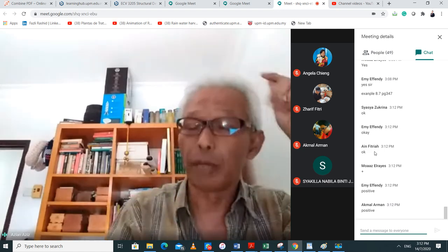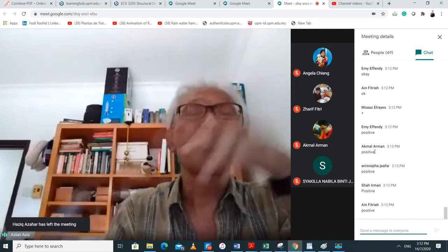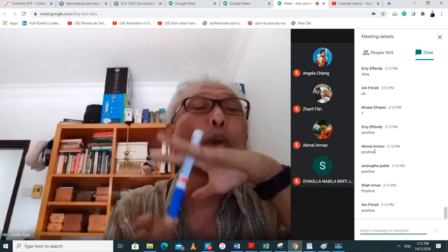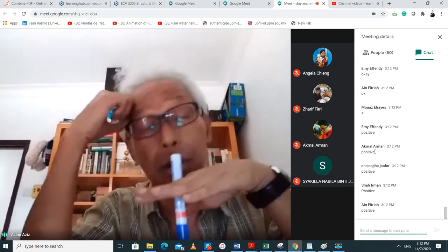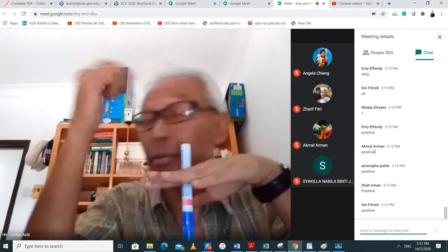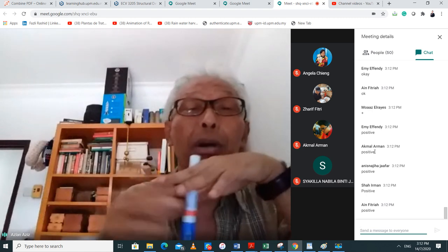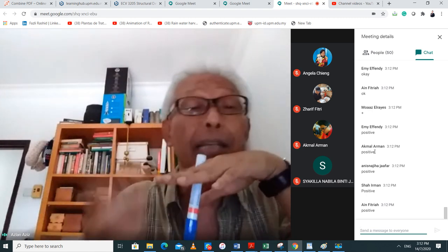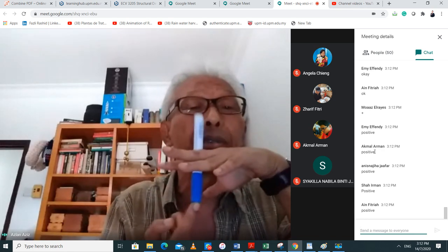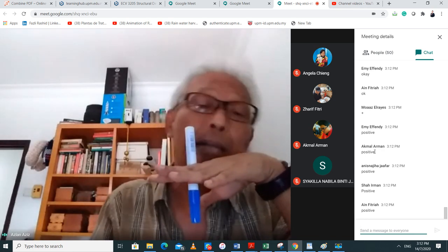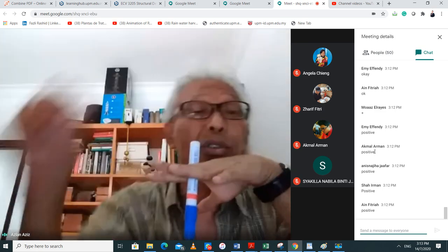Good for you, Muaz. So, positive direction, right? But you don't want this positive to be part of the bearing capacity of the soil. It is going to push my pile outwards. You don't want that, right? You want your pile to be taking care of the load given to you.